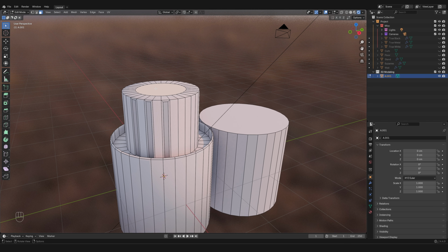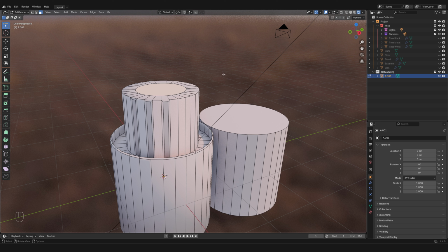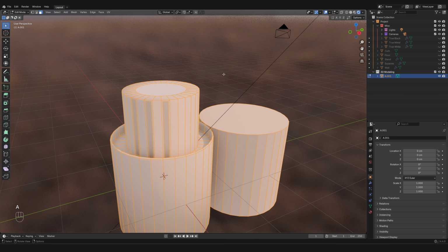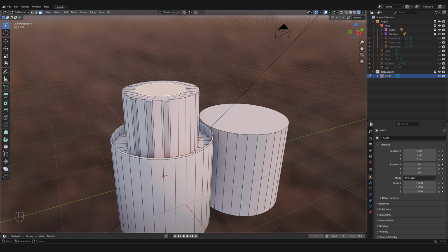Now beware that now this part has been brought back into the same mesh, but it sort of still exists as its separate mesh. And so in some cases, you might want to go through the process we just viewed of pressing A, M, and by distance. And now this face is once again part of this geometry. They are together and they act as one.